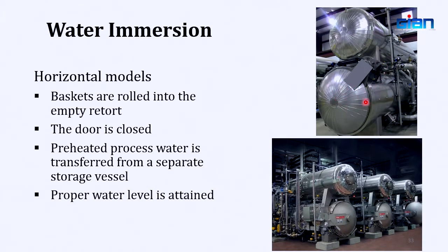And as it is entering, it's slowly filling up, and as it slowly fills up, it is giving some heat. So it's actually not maintaining 120 degrees C, if this is the temperature of the water in your upper vessel. During filling, there will be a small change in the temperature, but eventually once it fills completely with the hot water, you can inject some more steam to bring the temperature to the operating level.